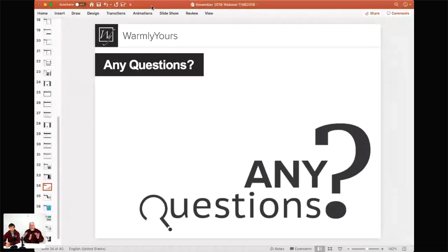And if you picture 15 minutes on a clock, it's heating all 15 minutes of those 15 minutes. If 2 of the 5 wavy lines are on, it's heating 7 of the 15 minutes, and the rest of the amount of the 15 minutes, it's off. That's what we call a duty cycle.